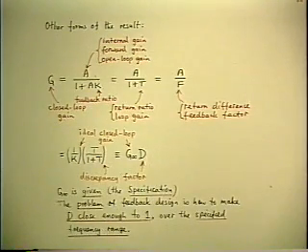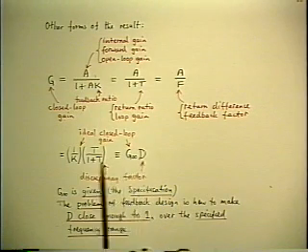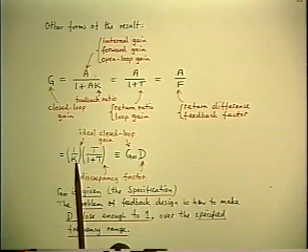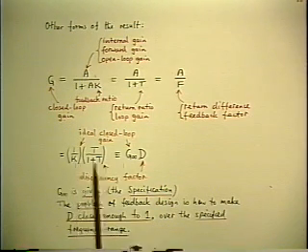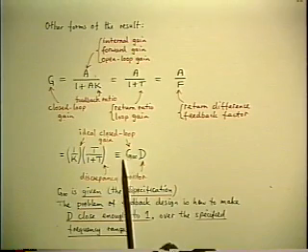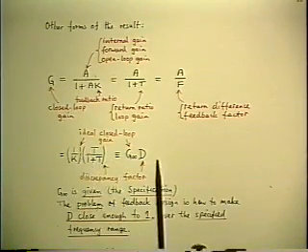So the hard part of designing a feedback amplifier resides in only one of the three requirements. The first requirement is you make G infinity what it needs to be, which means you design the feedback path independently to get the required G infinity. That's easy. The second requirement is you make T very big. That's easy.